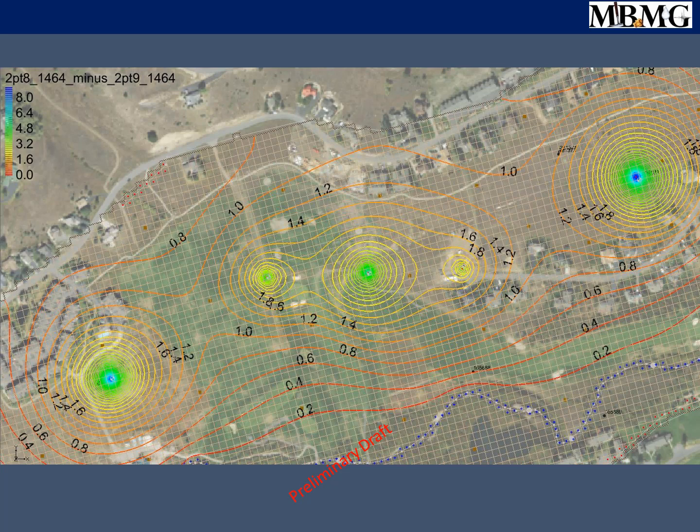And so this is showing all 5 wells in the model pumping for 1 day full blast, 24 hours a day for 1 day. And so it draws water levels down many feet. These are in feet. And it draws them down about 6 to 12 feet right at the wells. And that's very close to what, if we look at the aquifer test data for these wells, it's right in the ballpark for what are in those data.